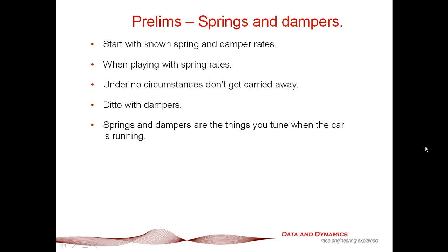Ditto with dampers. You'll play with the spring and damper rates once you actually start running the car. That's where the springs and dampers really come into their own. So I really want to ram that point home, because I've just seen a lot of cases where people start designing a new car and they come up with these crazy spring and damper rates, and you just take one look and go, okay, this is just not going to work. So I really want to ram home that precautionary tale.